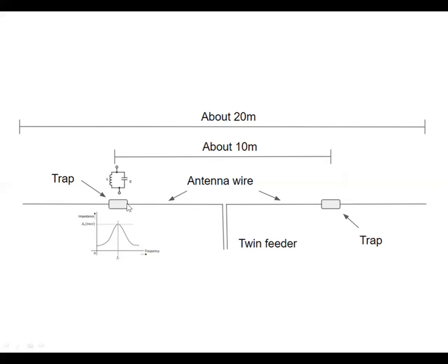That's a 20-meter dipole right there. So this thing responds as a 20-meter dipole. Then as you increase the frequency, the inductances and capacitances, the reactances of those elements change. So it becomes looking more and more like a short circuit, so that when you get to 40 meters, it's designed so that if you're sitting here at 40 meters, you see this length of antenna, which in combination with the trap circuit looks like a quarter wave dipole at 40 meters.